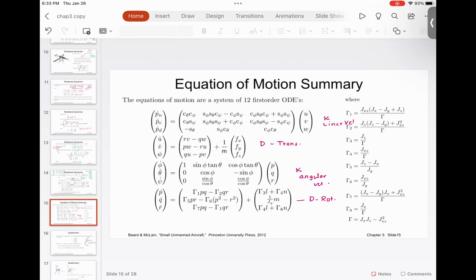However, there is a little twist. These equations are implemented in Euler angles, which means if you take these equations and try to simulate an F-16 or an aircraft that can do 90-degree pitch, or an aircraft that is doing a nosedive, that system will not work.